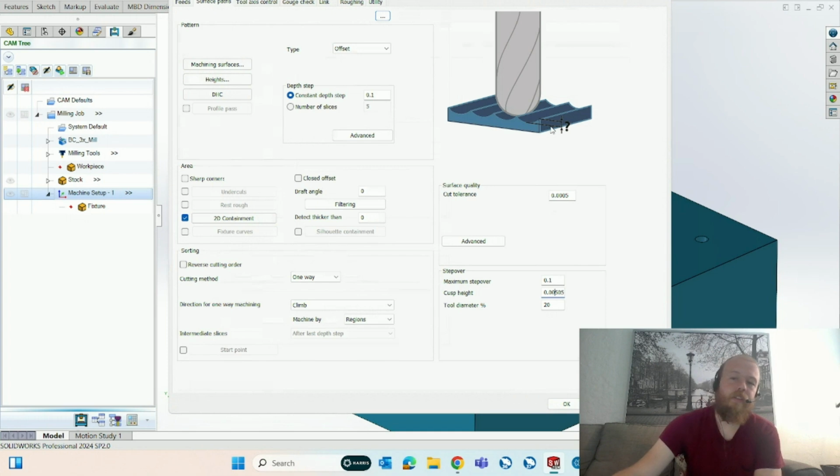So we're going to get into the simulation a little bit later and see what our roughing and finish pass is going to do, machining out the stock, and we're going to be able to view how much material is remaining, deviation based on the workpiece that we defined. Now in this one, there's not really any guesswork involved. You don't have to go into simulation to see if it's a tight enough tolerance level for us. We can just type in the tolerance level here.